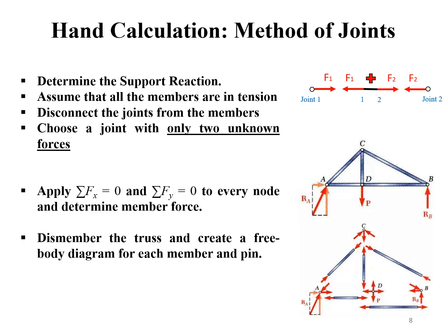If a member is in tension, the internal forces will be acting to make the member longer. For every action, there's an equal and opposite reaction, which means that a member in tension will be exerting a force on the joint, which is acting away from the joint. Please see the first figure. Of course, for members in compression, the force will be acting towards the joint.